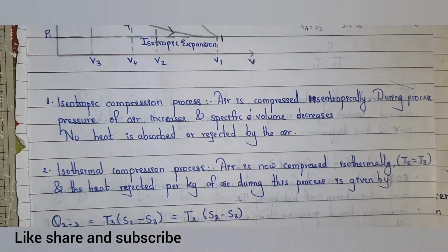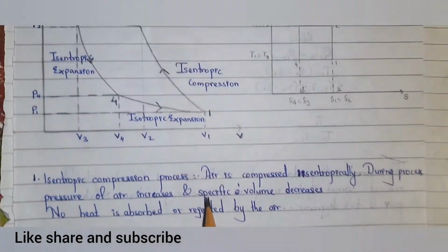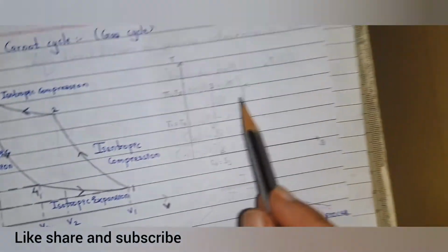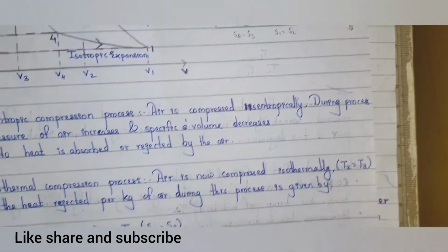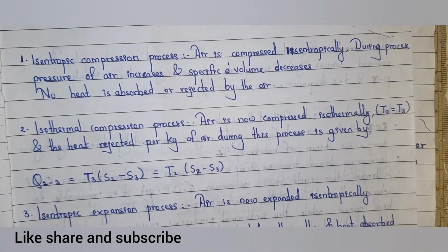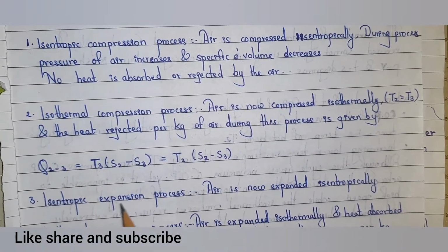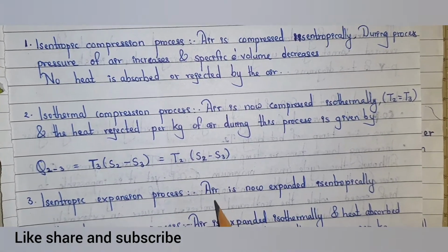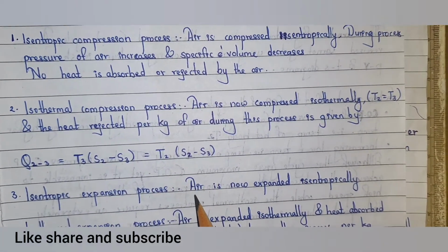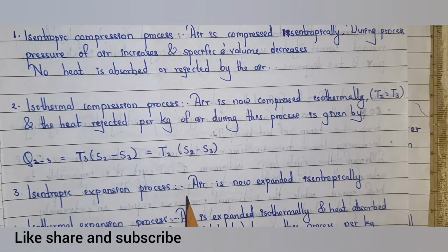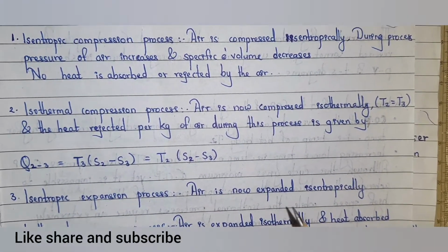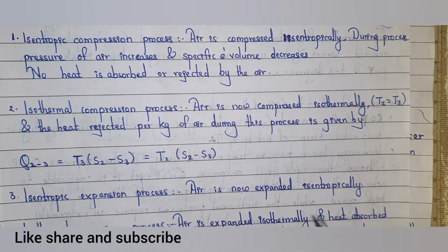Here T3 or T2 can be taken, as the values of T3 and T2 are similar. Now the third process, the isentropic expansion process, takes place, and air is expanded isentropically, in which no heat is released or absorbed.